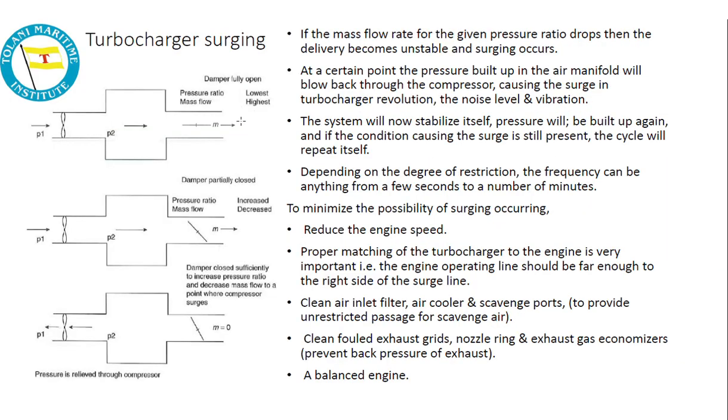Now when we talk about turbocharger surging, this is another phenomenon that occurs. If the mass flow rate at a given pressure ratio drops, then the delivery becomes unstable and surging occurs.